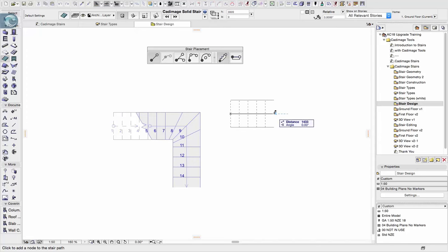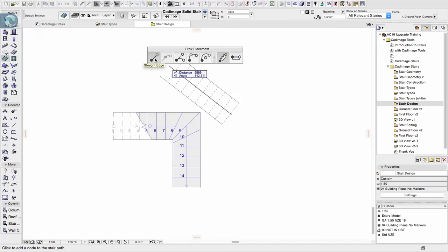This time I've gone for the central alignment. We have 5 options in terms of the geometry that we create. So this previous one I did was just an L shape with straight edges, but we have different curved options. So the first one, until I draw a straight section, that tangent is not going to be possible. So we can define a tangent, we can do a 3-point arc, or we can create a centre point and a radius to define the curvature.